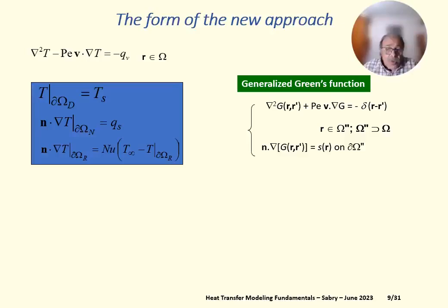As for boundary conditions, in the normal Green function they are homogeneous, but in the generalized Green function I cannot make this. Why? Because if I say, for example, the heat equals 0 all over the boundary, it will not work, because I have a heat source which is a Dirac localized somewhere inside the domain, and this Dirac will dissipate heat inside the domain, which should go out from the domain.